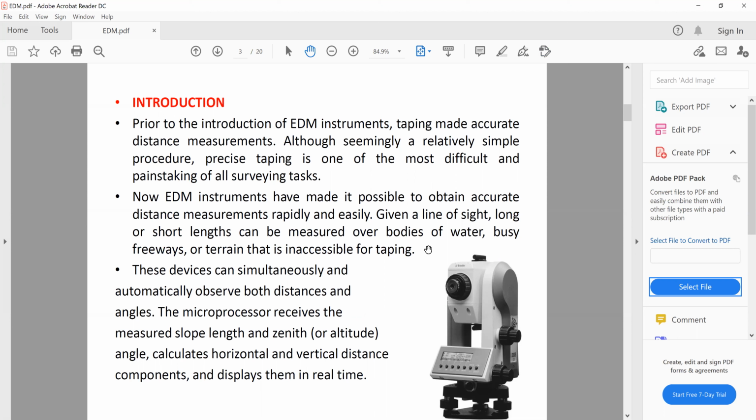On the other hand, if you have this instrument over here, it can do that work in a lot lesser time and with much more accuracy. So that is why this instrument has gained a lot of importance. Some total stations have this instrument inbuilt as well. We have different versions of this instrument. We have the handheld EDMs, and then we have these tripod ones, which basically look a lot similar to a theodolite.